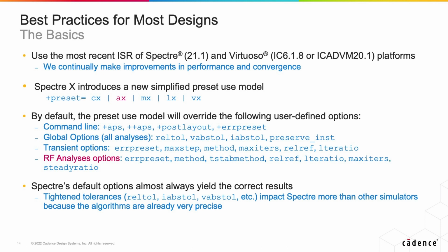Once you have figured that part out, if you're going to do small signal noise after that, you have only one choice. If you have chosen to use HB, then when you go to small signal noise, you'll use HB noise. You don't have any other way of doing it, because for any small signal analysis, the large signal steady state operating point has to be calculated first. So if you do PNoise, you would have had to finish PSS.